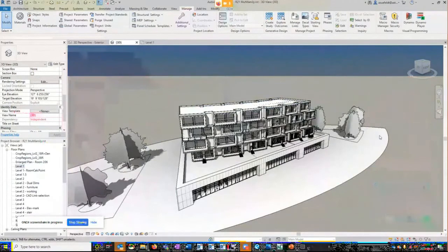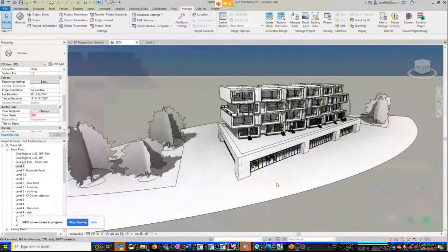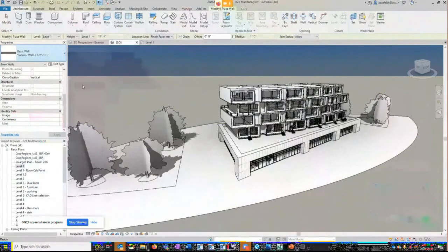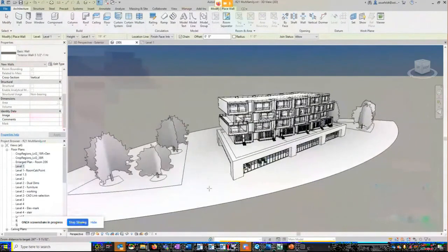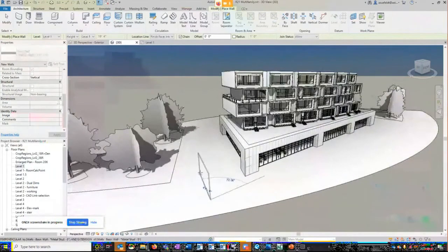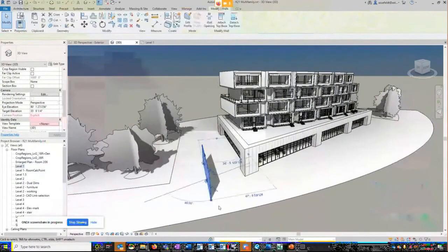So first thing that I want to show you is actually the slanted wall tool. So I'm going to come up here. I'm going to make a wall. WA is my shortcut for that. I can also come up here, right? And I'm going to draw a wall in this project. And I could just use an existing wall, but let me just do this for now. So here's a wall. Just kind of just hone in on that.